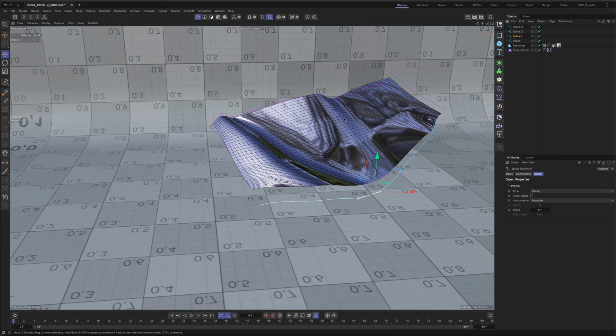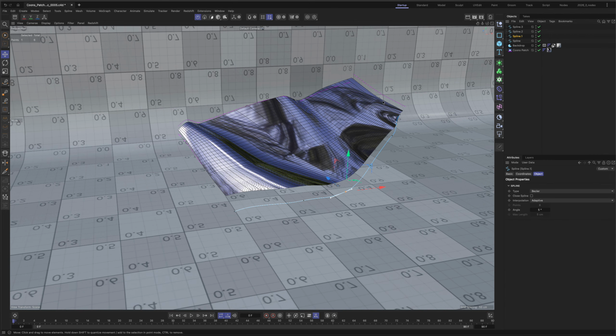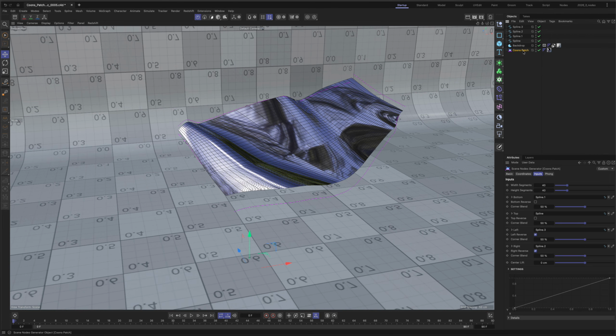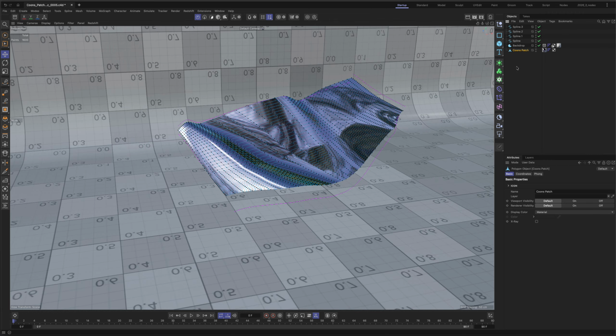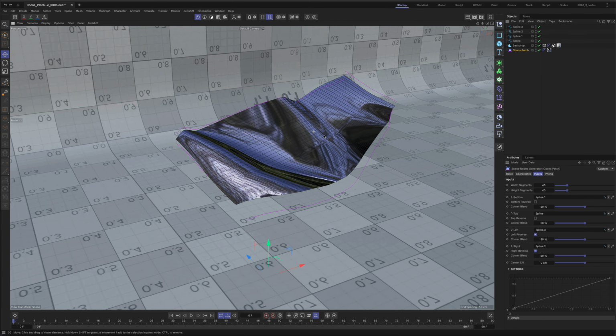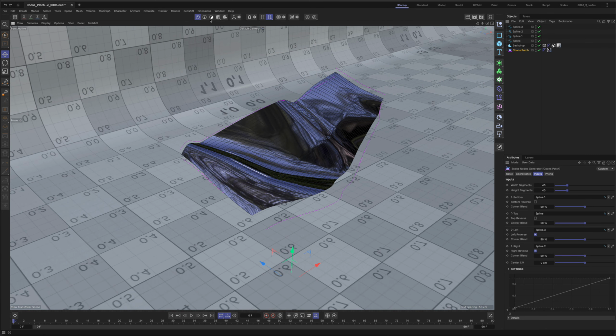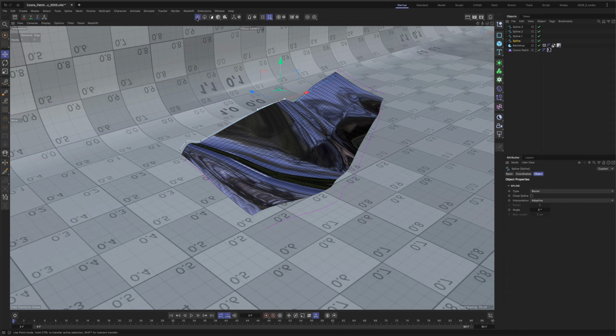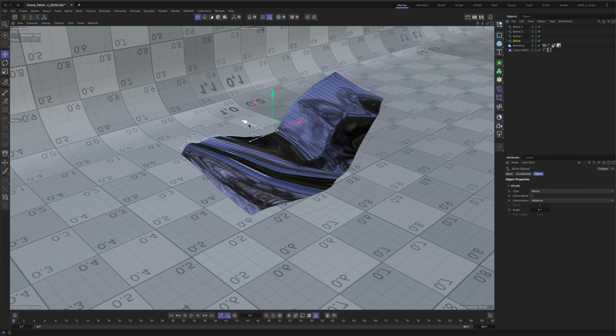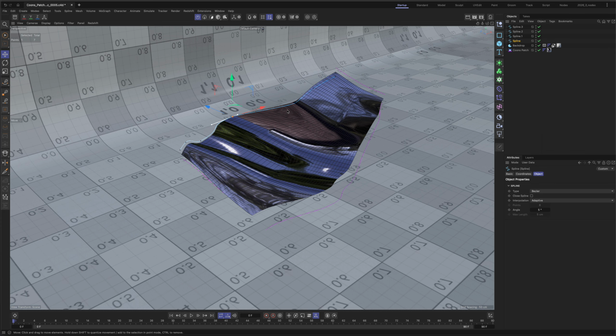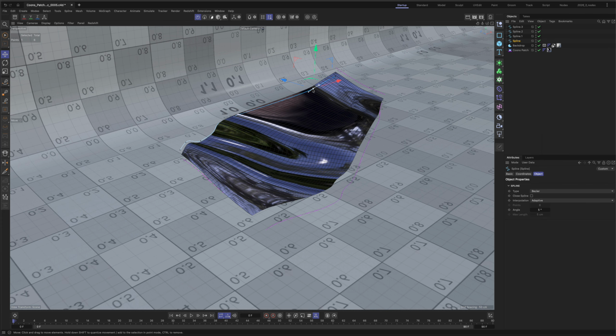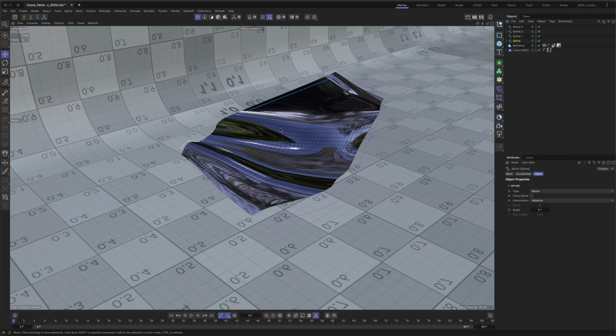What is also great about it, it is working just as any other generator. So I simply convert it if I want a polygon version of it, and you will get the UV coordinates, of course. And last but not least, let's select this spline, just to manipulate the surface a little bit. And let me show you that you can delete the points as well. It will always interpolate.